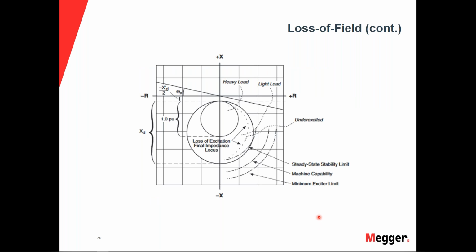In the electromechanical world, there are many electromechanical relays that are used for the setup. And in the microprocessor world, of course, we only have one that can actually handle multiple elements at a time. So usually, when you're testing a loss of field or a 40 relay, sometimes there's a couple of relays involved with that. We'll have to test the timer. We'll also have to test the relay itself and make sure everything is working properly together.